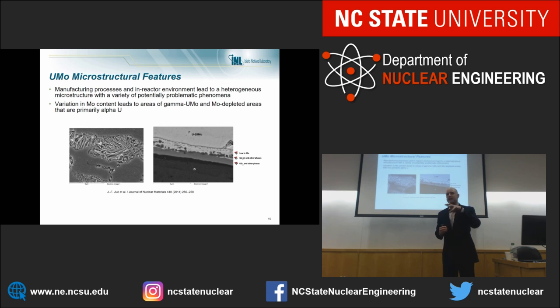Deconstruction of the fission gas superlattice leads to very large bubbles, which leads to lots of swelling. So we want to minimize the amount of decomposition of these fuels, minimizing the population of additional dislocations the fuel starts with, so that we can delay the onset of recrystallization and accelerated swelling behavior.